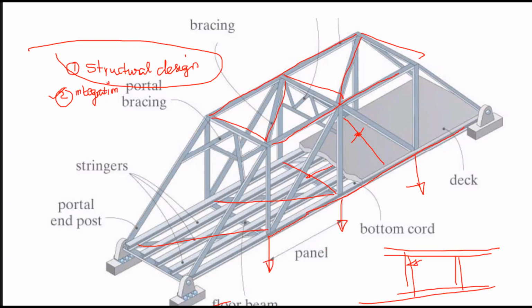Why should I have the truss in the horizontal direction? It is because you have some wind loads coming on this, right? Now, these loads are in the plane of the truss. What about the vertical load? The vertical load is also in the plane of the truss, and similarly the horizontal load.